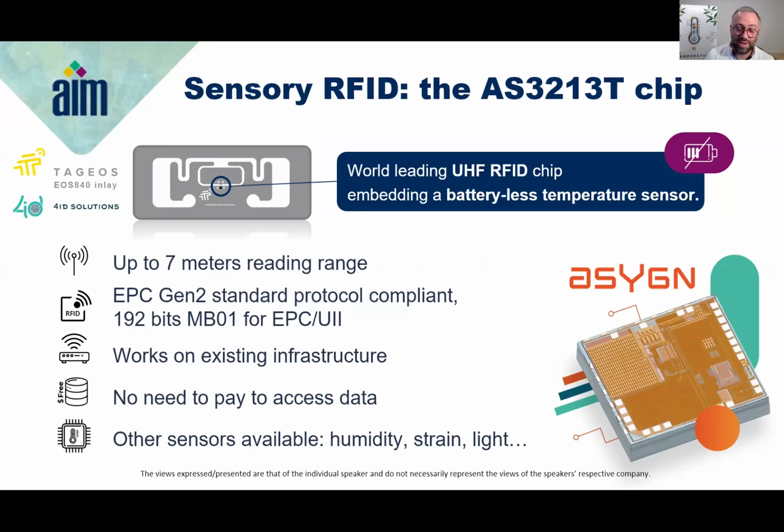This chip is, of course, batteryless, like most RFID chips, and is perfectly capable of the EPC Gen 2 protocol. It is perfectly compliant, so it will work on your existing infrastructure, and potentially any infrastructure. Those tags perform like standard RFID. If you don't know that they are able to read temperature, they just act as a standard RFID chip. And then if you know how to unlock the potential, you can read temperature, but also humidity, or strain, or light, or potentially any other sensor that you connect up to those chips.